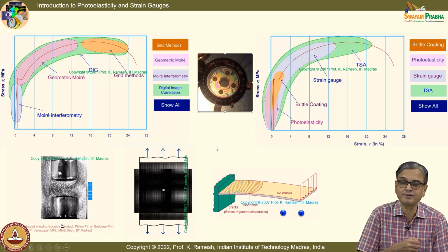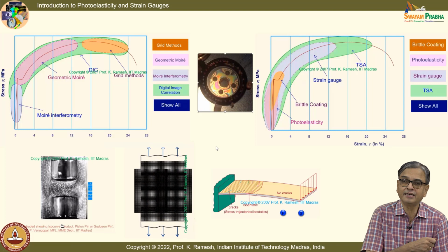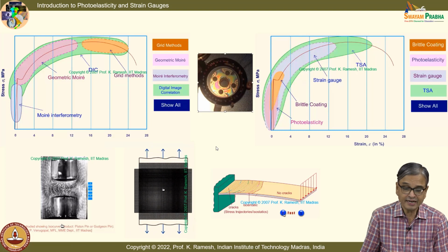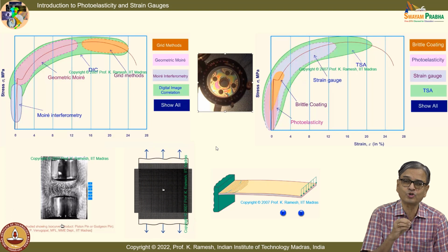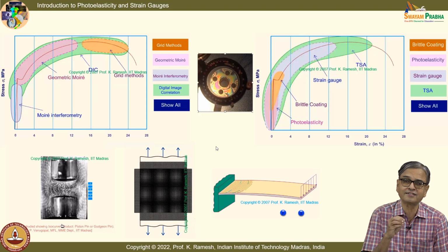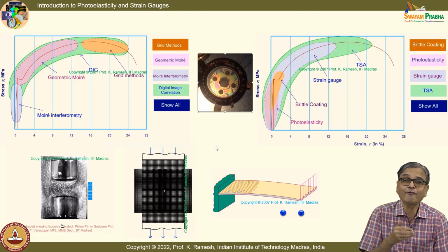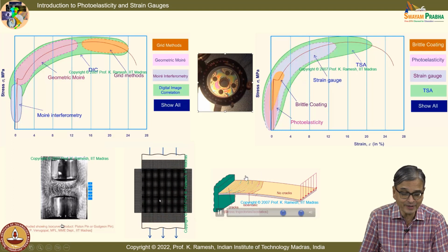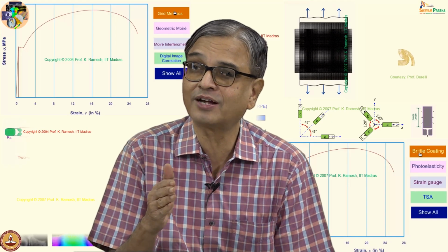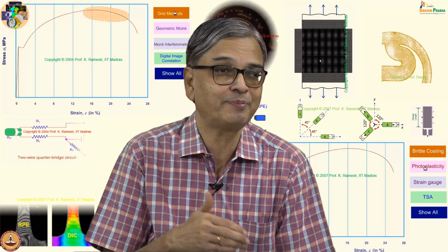We have said that we will spray a brittle material, and it is very interesting. It is a brittle material. So, when the normal stress reaches a critical value, you have cracks formed. So, in this technique, cracks are information. Normally, you are worried about the crack developed in any structure.